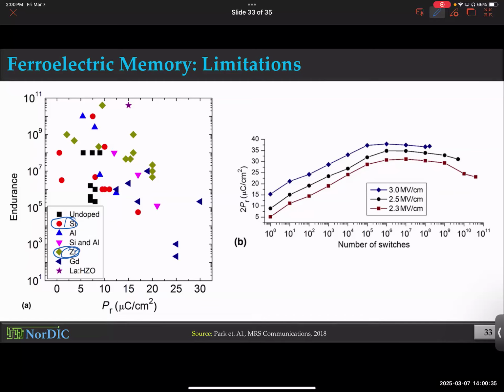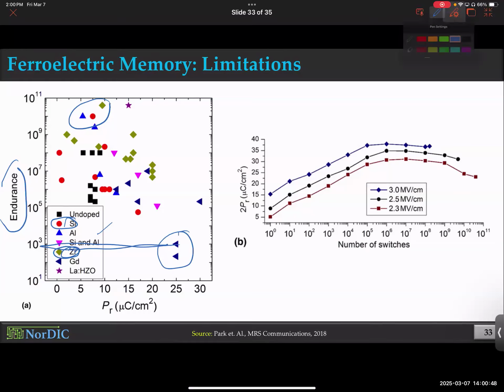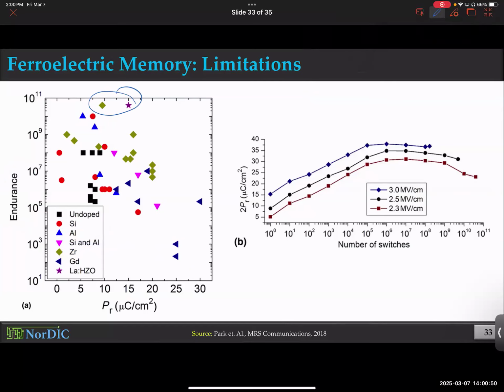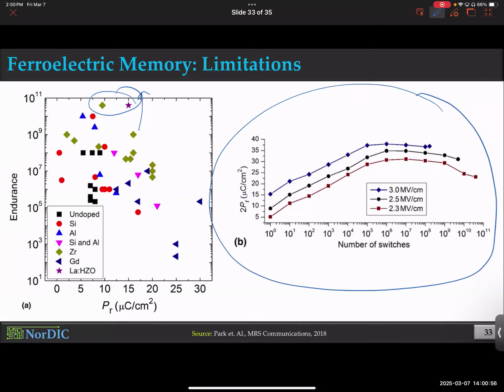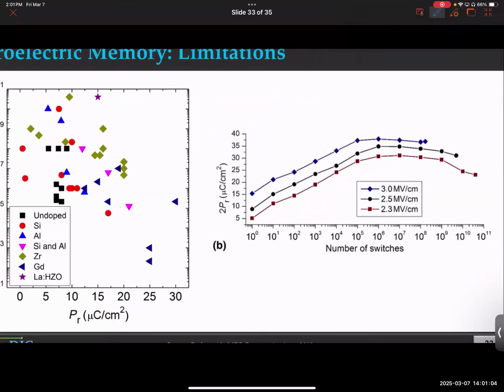So notice, in terms of endurance number, they are not too bad if you use the right dopants. So you cannot just negate them based on these numbers. Hey, 10³ is nothing, but don't shoot for 10³, shoot for 10¹¹ and beyond. That's the endurance number we like. And this is just taken from a different source, but it gives you the same picture. Wake up and then fatigue. And the answer to your question also lies here.